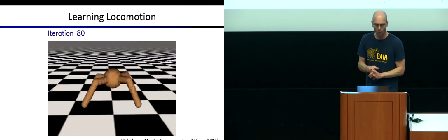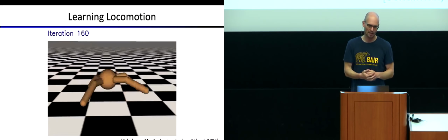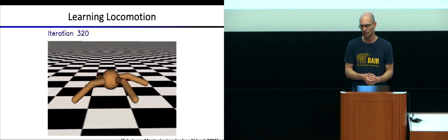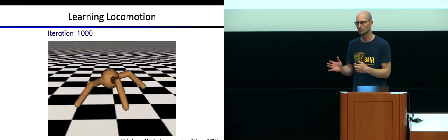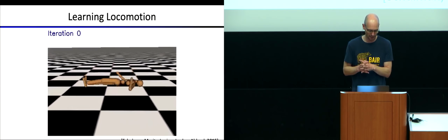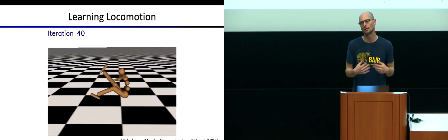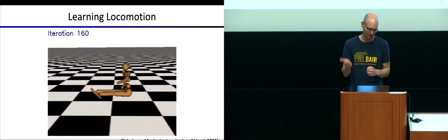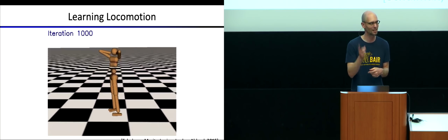Now, with this in mind, of course, if you look at the amount of data collected, that's still a little tricky. It takes a good amount of data collection before this robot has learned. If it's a physical robot you're trying to train, it gets tricky because you might break it before it has learned enough. And even if it doesn't break, it could take an unmanageably long time to get the amount of data you need. But it shows in simulation, at least, a lot of progress towards learning intelligent locomotion behaviors. Here the reward function is the closer your head is to standing head height, the better. So sitting is better than lying on the ground, and standing is even better.